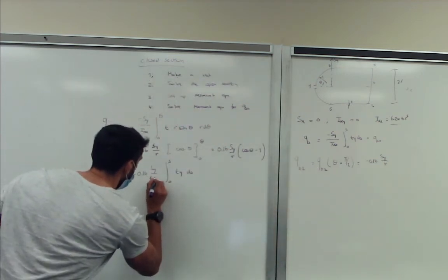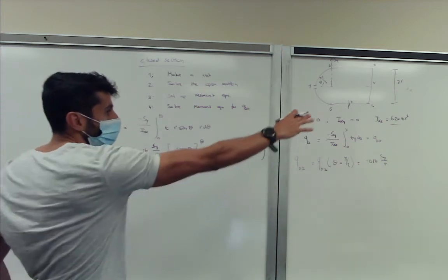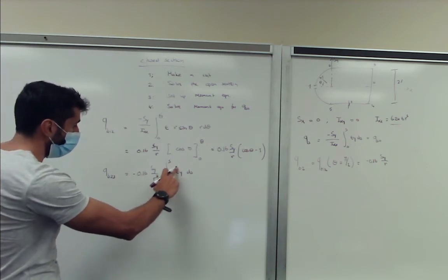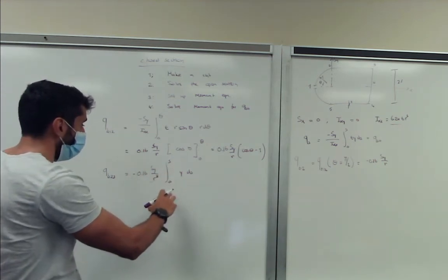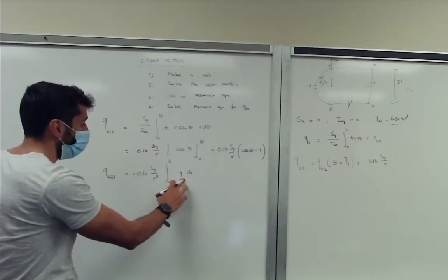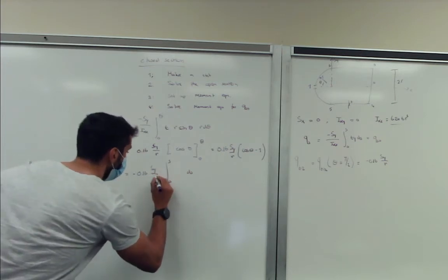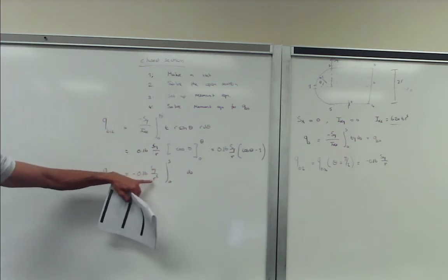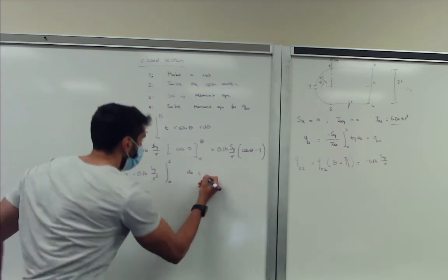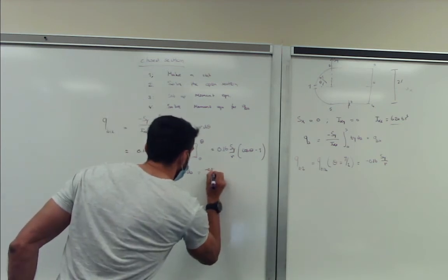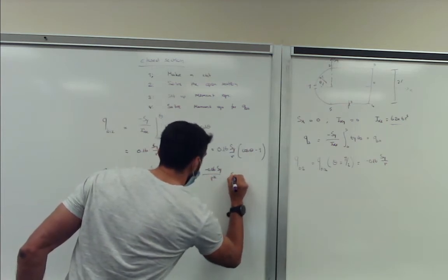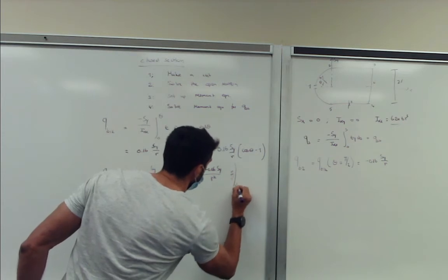Let's call this t R cubed from the Ixx. So we know that, of course, the t's cancel, so we can get rid of those. And we know that y was equal to R. The y location doesn't change with s, so this cancels with one of these. So we get 0.16 Sy over R squared, integral 0 to s of ds. And this becomes basically 0.16 Sy over R squared times s, and s goes from 0 to 2R.